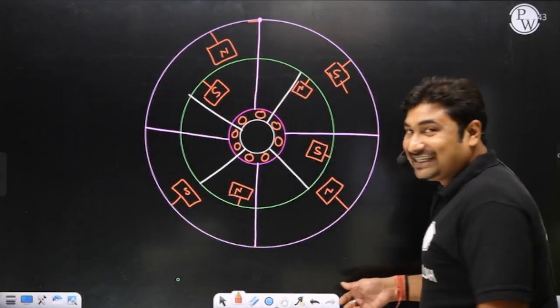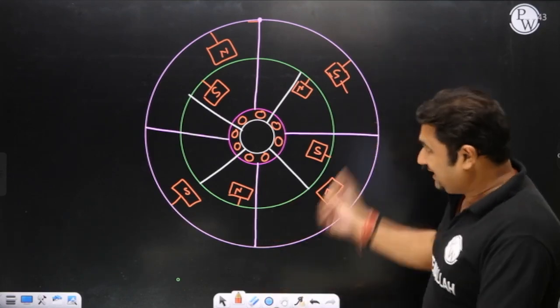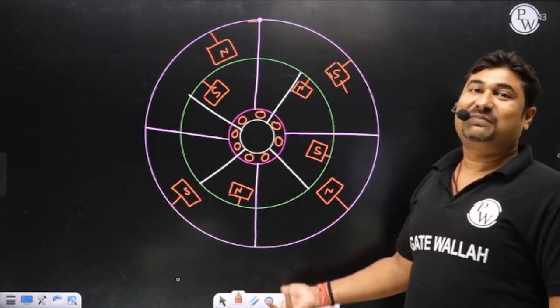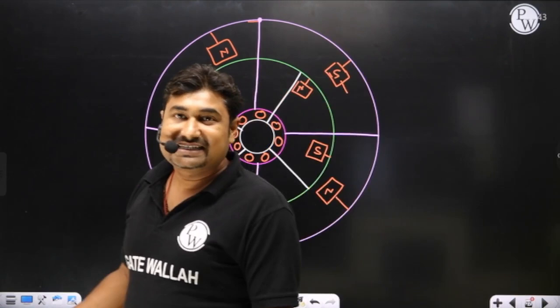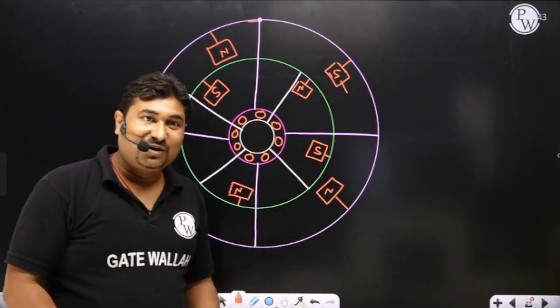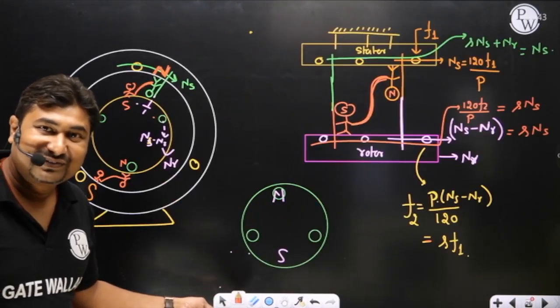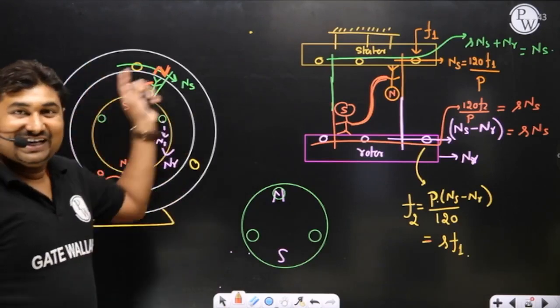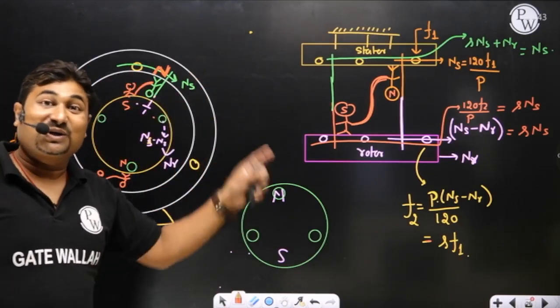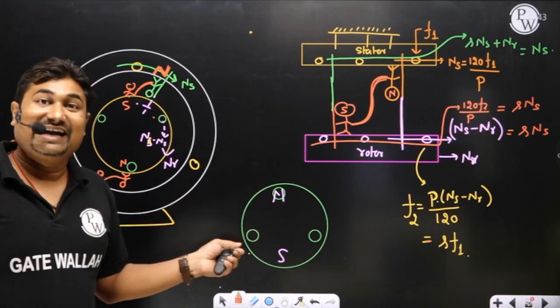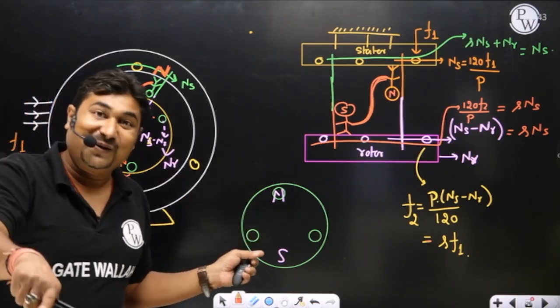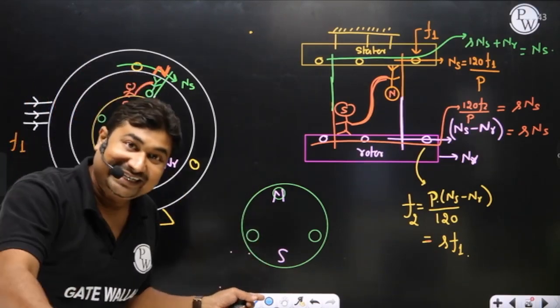Now with the 3-phase induction motor, the greatest advantage is we need not rotate the stator. We just need to supply a 3-phase supply to a 3-phase balanced stator. It will create a rotating magnetic field by itself. This rotating magnetic field, while revolving round the rotor, cuts the rotor conductors, induces EMF and creates rotor poles. The rotor pole is also rotating.